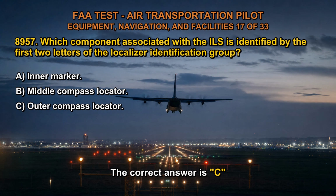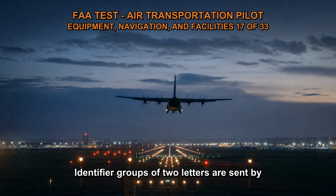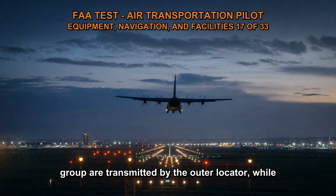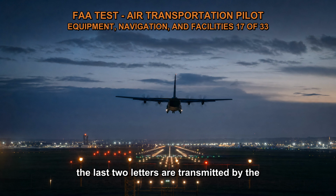The correct answer is C. Identifier groups of 2 letters are sent by compass locators. The first 2 letters of the localizer identification group are transmitted by the outer locator, while the last 2 letters are transmitted by the middle locator.